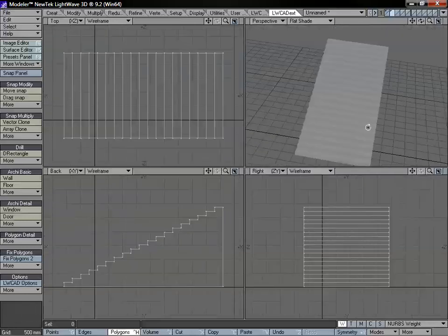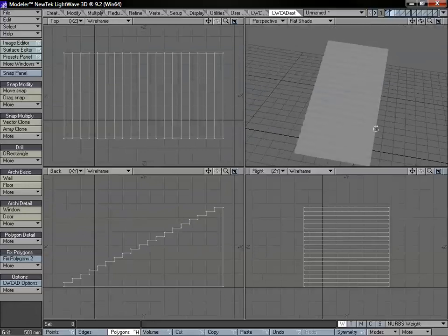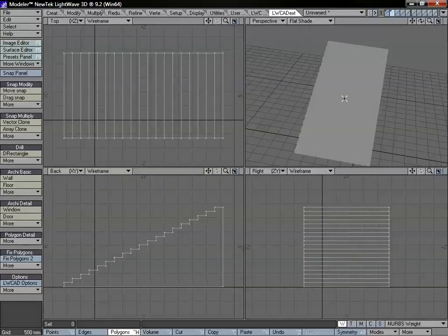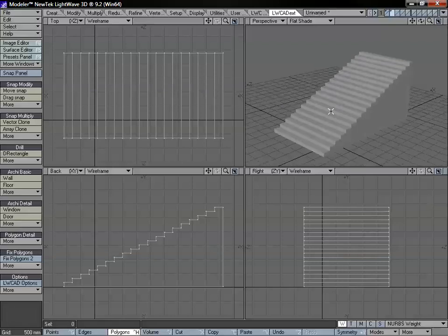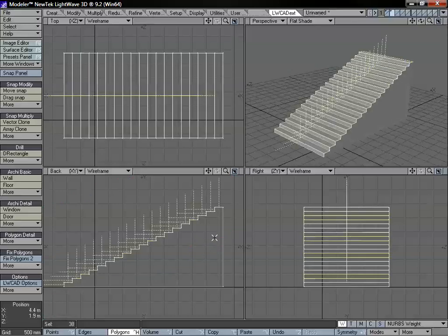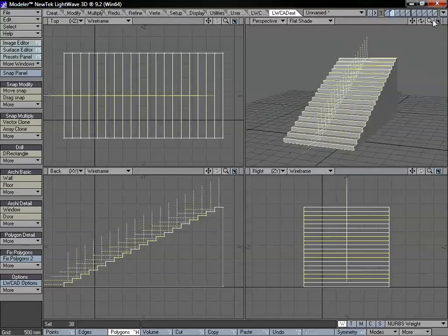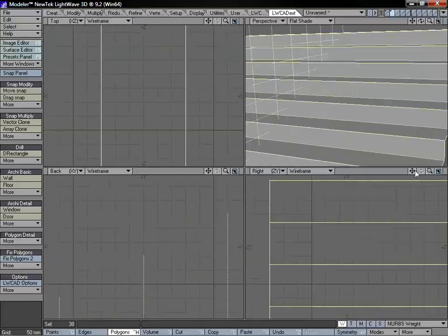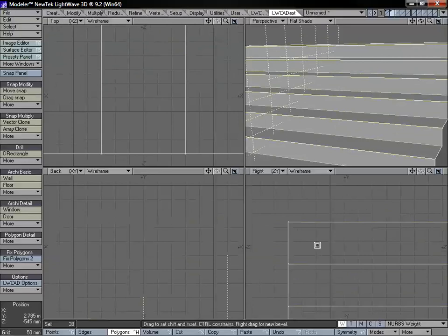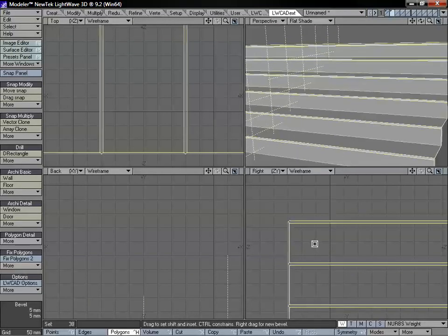And if you do need to get maybe a little bit of extra depth, because you can see that at some points when we look at certain objects from certain lighting angles, in this case if we take a look at these stairs right now, we can't really tell they're stairs. So a really easy fix for that would be to bevel all of these different polygons that we have. So if I just select all of our stair polygons, I can just zoom in fairly close, or we can do this numerically. I'm just going to hit B on the keyboard, and we can just bevel that.